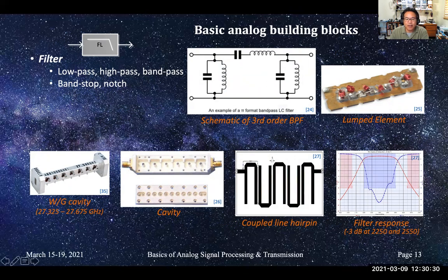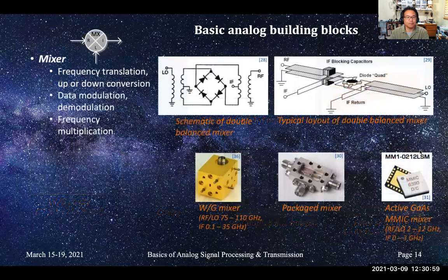So it is a bandpass filter with 1, 2, 3, 4, 5 sections, because the number of sections is proportional to the steepness of this stop band. You can see this blue trace is 20 log rho, or the reflection coefficient. So almost all the signal gets reflected here, and that's why it's a stop band. You get to the pass band, most of it doesn't get reflected, and then back to the upper frequency where almost all the signal is rejected.